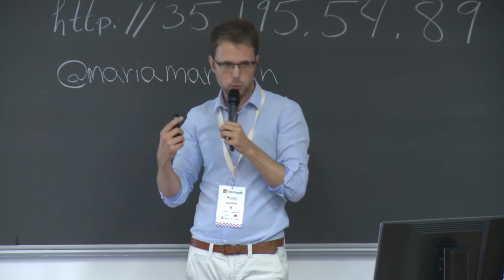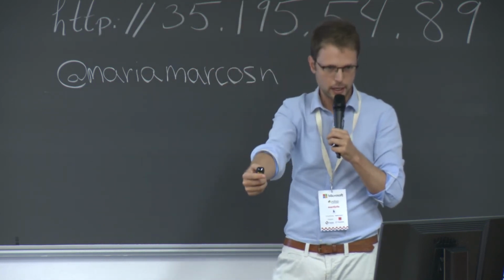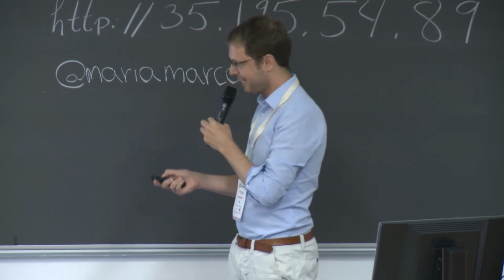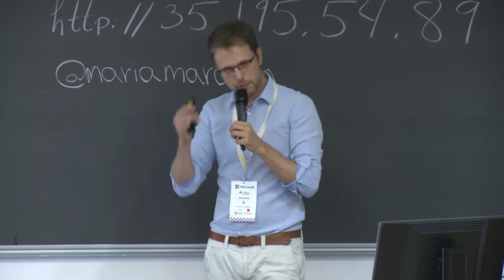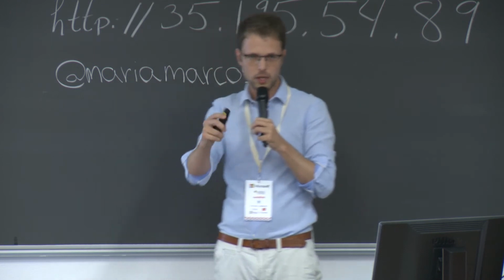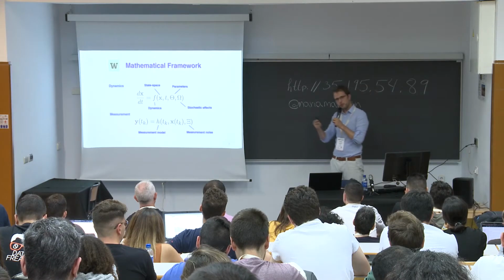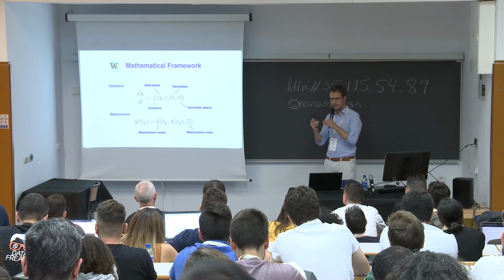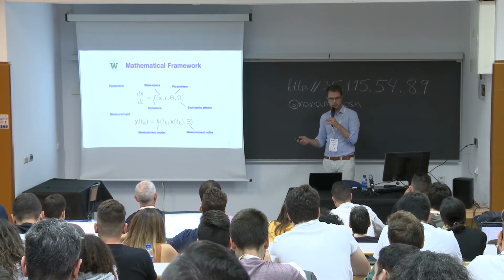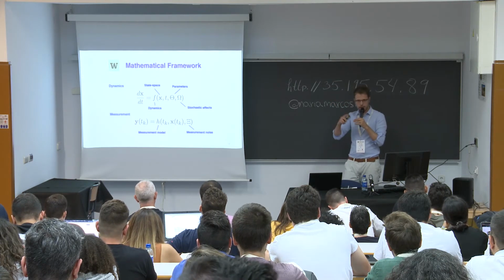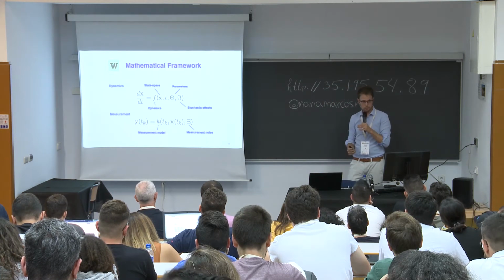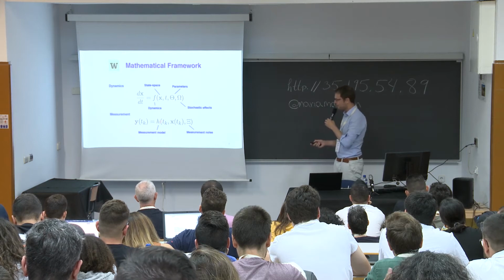So what can I do for the next instant in time to improve or control my process? What can I do to change something over time? And this is very, very important. Because if you put your target over time and you don't care about how the target changes, probably you will not find things that you can change in that period of time. So always think about your target changing over time. If you have a lot of seasonality and things that you don't care about, when you take the difference between 2 consecutive times, the seasonality moves away. It's a very common trick. But you can go further.